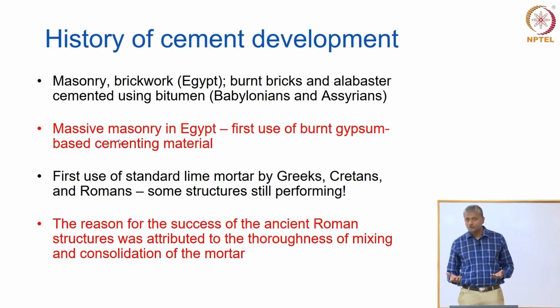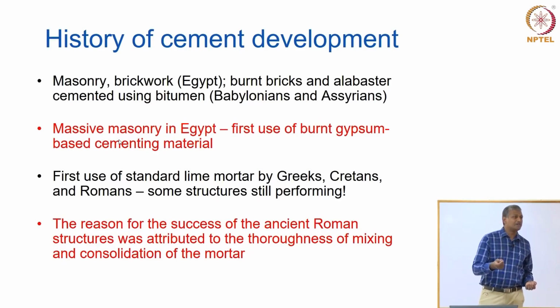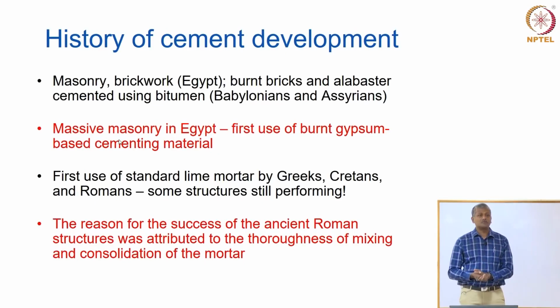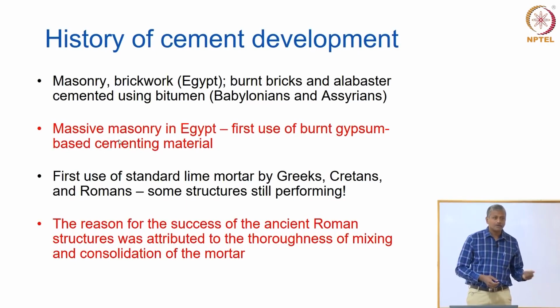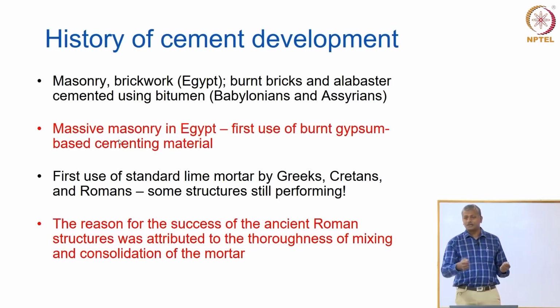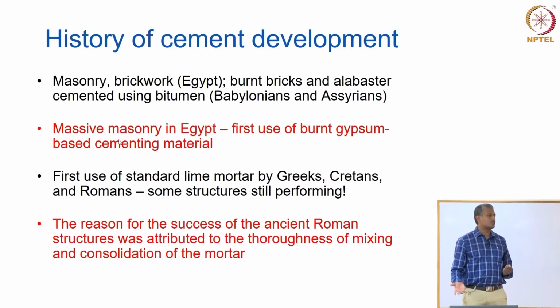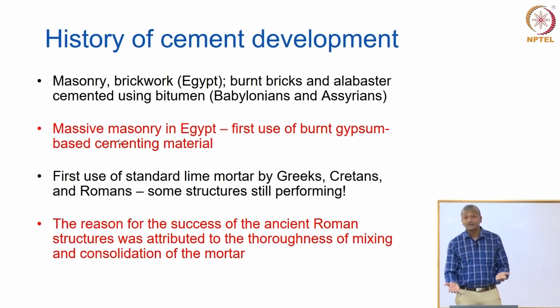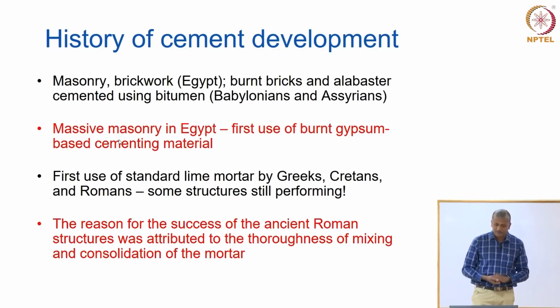Now, today we know that bitumen is used to actually pave roads, right? But the same material was earlier found in natural pools. Okay, you know the process of formation of bitumen, right? It's formed from the process of distillation of your petroleum or crude oil. You get several products like gasoline, kerosene, all those kinds of things, and what remains as a residue is asphalt, right? This asphalt also occurs in naturally occurring pools around the world, and people were actually able to extract this asphalt and use this as a binder to bind these masonry blocks together, okay? So, that became the first sort of binding material to start binding these masonry blocks.